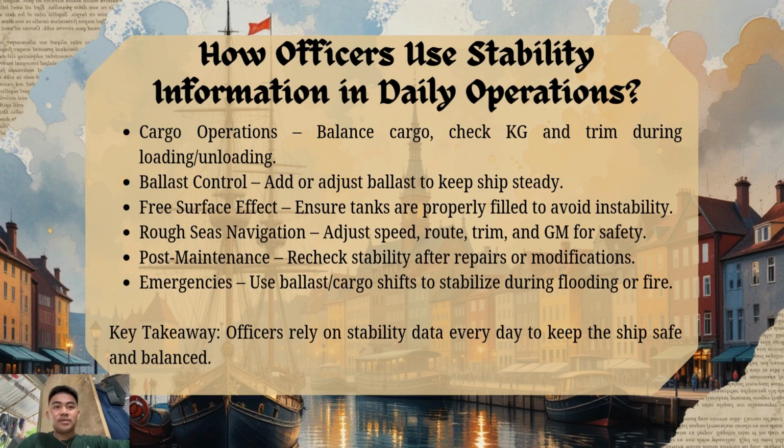How officers use stability information in daily operations. Cargo operations: balance cargo, check KG and trim during loading and unloading. Ballast control: add or adjust ballast to keep the ship steady. Free surface effect: ensure tanks are properly filled to avoid instability.